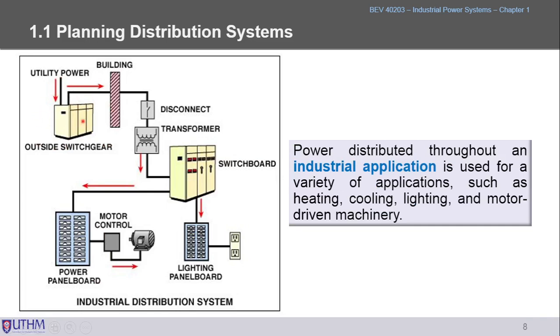And this is what you can see from the IPS. So you have the switchgear. Inside the switchgear we have the transformer as well. We have the transformer which might step down further. Let's say just now we have the distribution transformer stepping down from 33 to 11, and then if we have an application in the factory with another kV, say 6.6 kV, for example, where can we get the 6.6 kV? From 11 kV we need to step down further, right, to 6.6 kV or 3.3 kV. So this transformer is located inside the switchgear here, right?